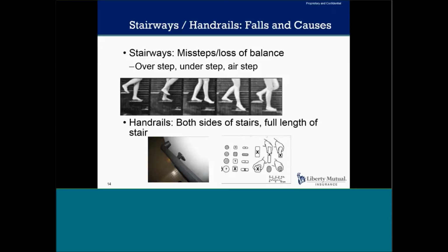Either way, the handrail is the only thing separating the pedestrian from certain injury, or worse yet, the threat of not being taken seriously about stairs. A handrail is not useful if it cannot be gripped, and the dimensions here offer good guidance. Decorative handrails, like the examples with the X, are not recommended, but yet we see them all the time in our buildings. If you need to replace or add handrails, please use a style more conducive to better grip, like the ones indicated here.